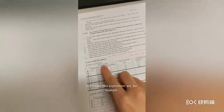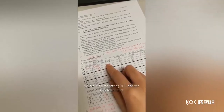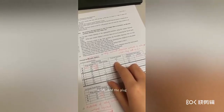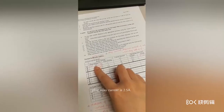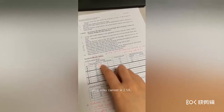Let's take this set for example. We say the time setting is 1, and the current injected is 5 amperes, and the plug setting relay current is 2.5 amperes.